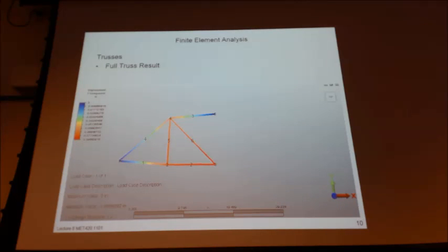Okay, so we can take advantage of the symmetry, and for many of our models, it'll make a difference and be worthwhile to do so. And you just have to understand how to constrain it and how to interpret your results so that you're treating it as if it was the full piece.